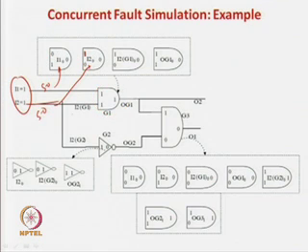Now, we already told that this net is a fan out net, so it is different. I2 G1 stuck at 0 is also possible. Stuck at 0 here and stuck at 0 here have the same effect: 1 0 and the output is 0, but you have to keep both versions because they represent two different faults.